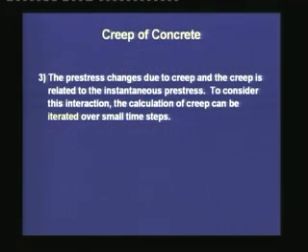The third consideration is that the prestress changes due to creep, and the creep is related to the instantaneous prestress. To consider this interaction, the calculation of creep can be iterated over small time steps. We have to remember that the creep depends on the prestressing force, because the creep strain is equal to a certain factor times the elastic strain.